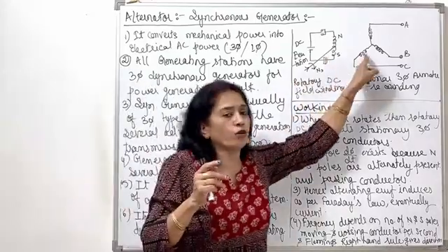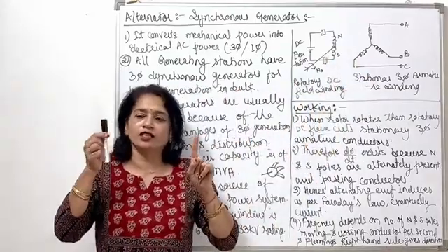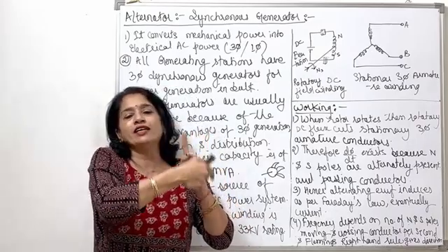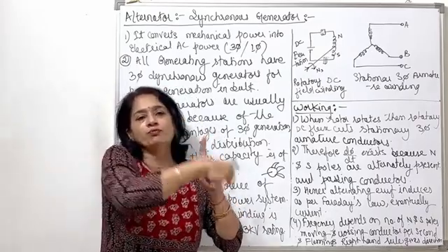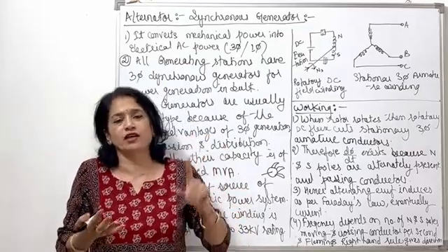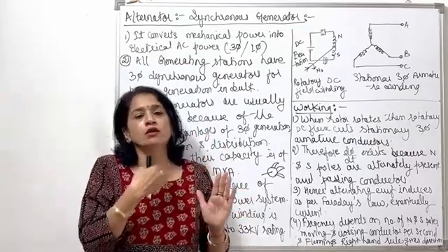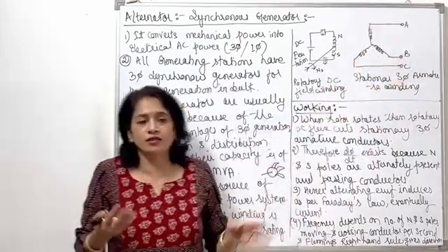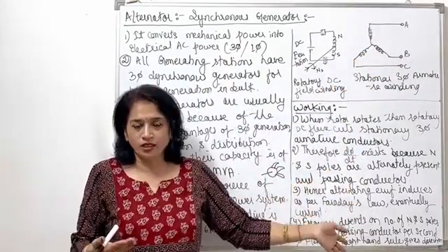But with these electrical circuits, I can explain that as the north and south poles turn, the flux linking to the 3 phases, A phase, B phase and C phase, varies with respect to time. So there is a rate of change of flux with respect to the armature conductors. That's why EMF is induced.